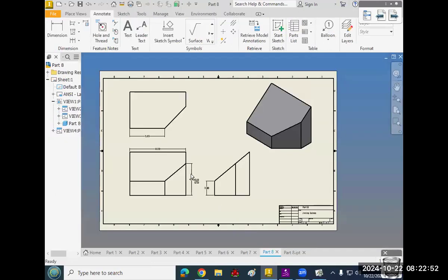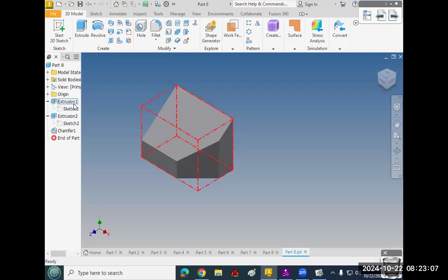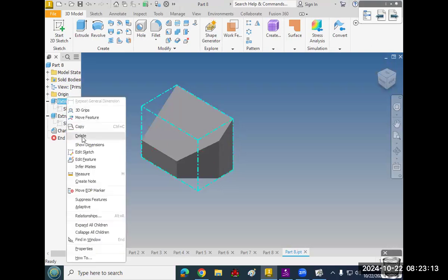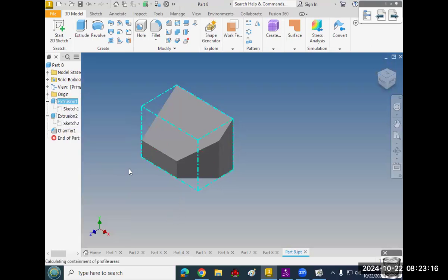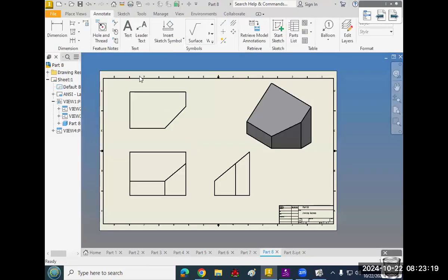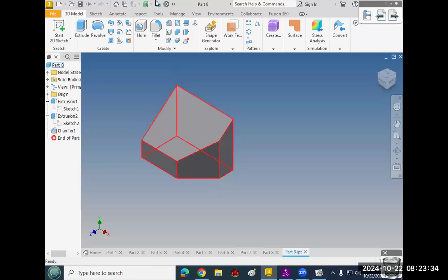Let's work through this the other way and see if we can just do the dimensions that we needed to make it and then rearrange things. Okay, so we needed to start, we needed total width, total height, and the extrusion, which was, I just showed it, 5. Okay, so let's go back here. We need total width is there, total height is there, and extrusion, which is total depth, is there. Okay, so that's the first part feature.